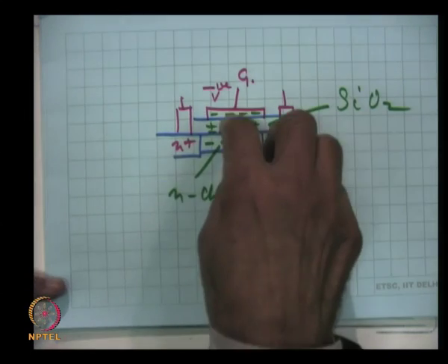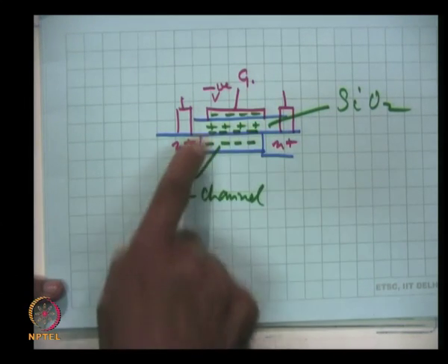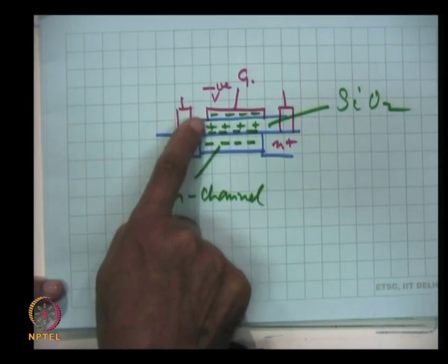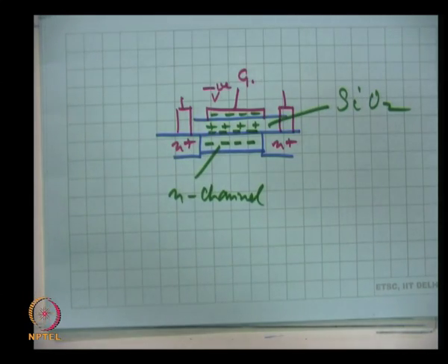So, the field at the gate will induce the opposite charges. You must have studied how the capacitance of a capacitor is increased by introducing a dielectric. The dielectric gets polarized and that nullifies, in the case of a capacitor, some charges of the plate. So, the capacitance increases.